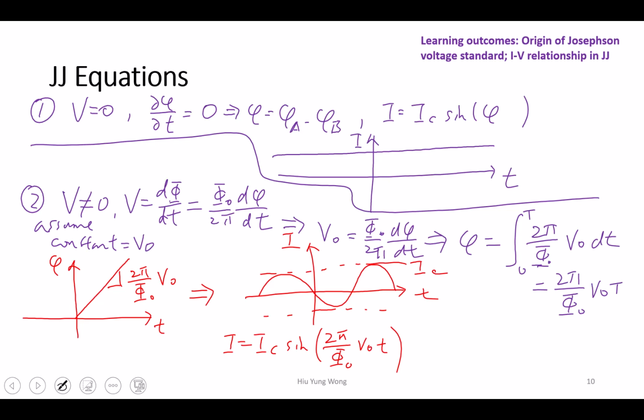So you do not think that you can go more than the critical current, because after critical current, you start breaking the Cooper pairs, you go back to a normal state, no longer superconducting state, right? And then your Josephson junction is not going to work as what you want. Yeah. So this is an important concept.